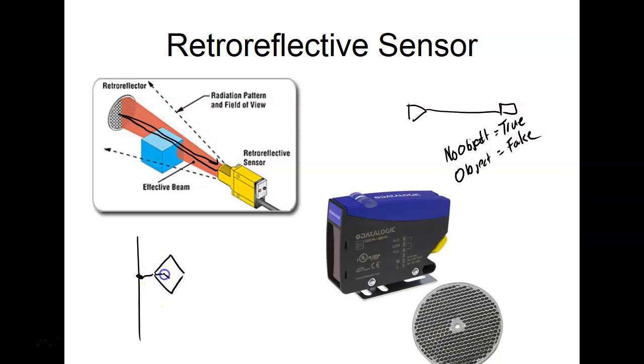So here's my solid state. And then, of course, it's a 3-wire sensor. So we'd have this running over here. I would take my output and I would move it into this amazing thing called a control relay. Now, not only out of a control relay can I get normally closed contacts, I can also get normally open contacts.